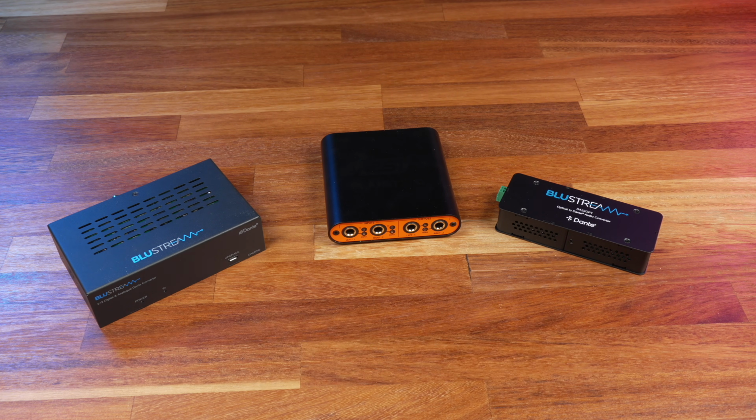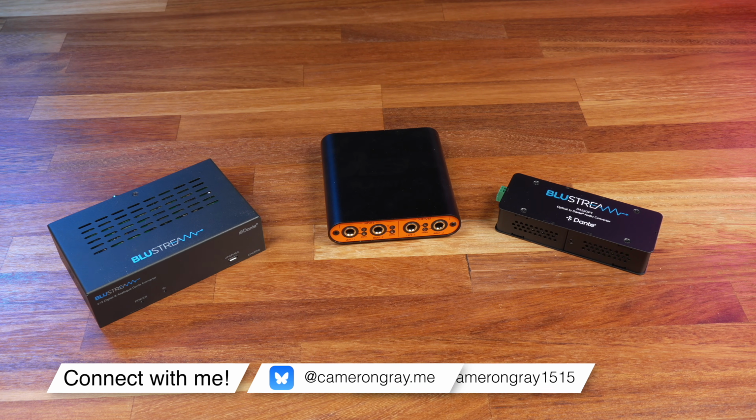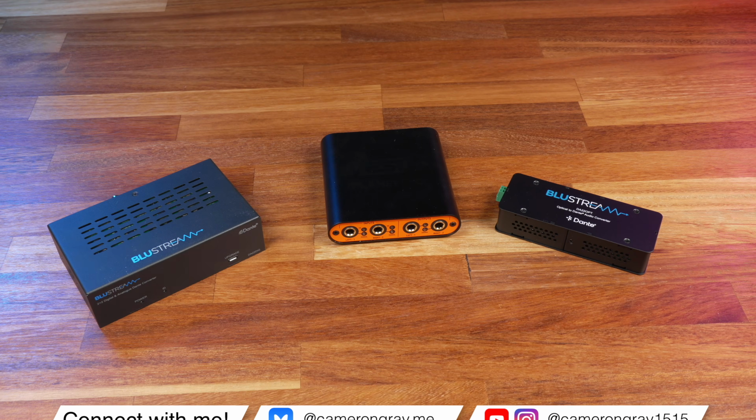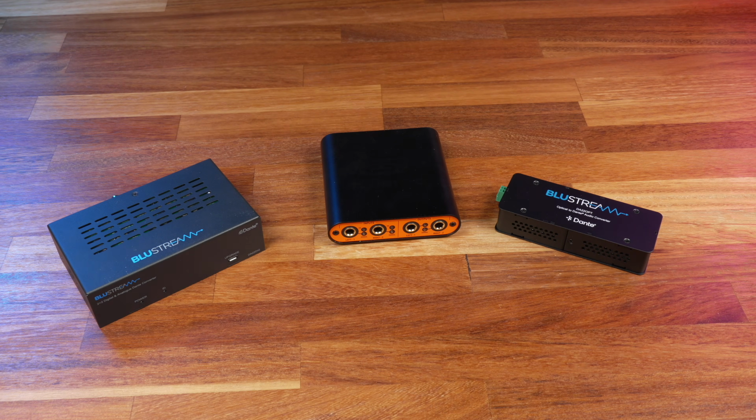However, I want to also be able to send audio from all my TVs around the house into the system so that I can listen to TVs through the ceiling speakers. Of course, one way I could have done that was just to run dedicated audio cables from each TV down to the rack. But the issue with that is analog audio signals are prone to interference, so running them long lengths through a building where the cable might end up close to mains electricity isn't really ideal.